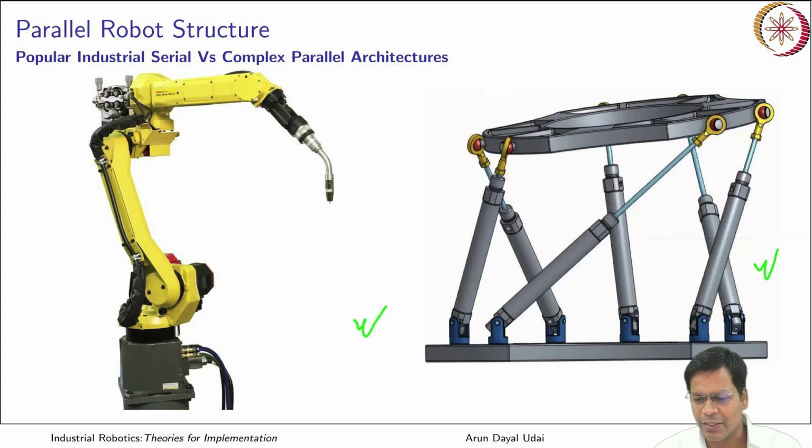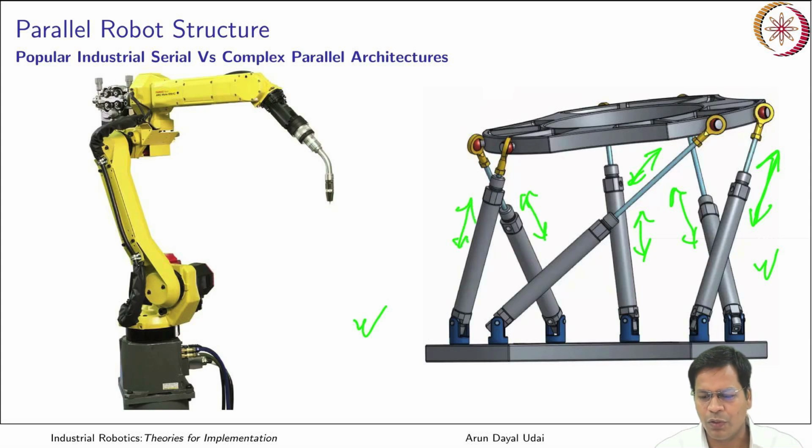So yes, these are actuators. You see, it has one linear actuator that can make this kind of motion. It has another linear actuator, yet another one, you have another one. So this is nothing but a Stewart Gough platform. Okay, so it has 6 linear actuators that connect the bottom platform using a spherical joint here and maybe a universal joint here, or it can go otherwise. So it is universal here, prismatic here and spherical here.